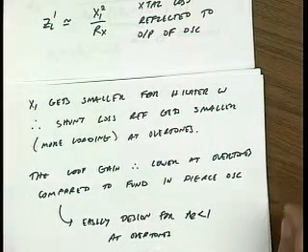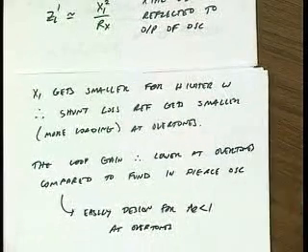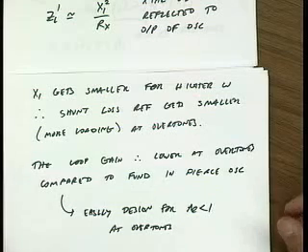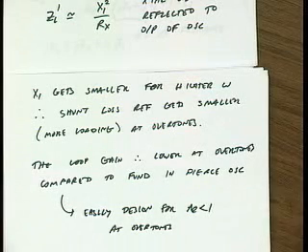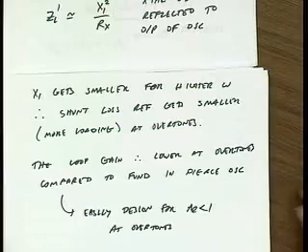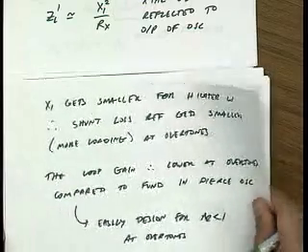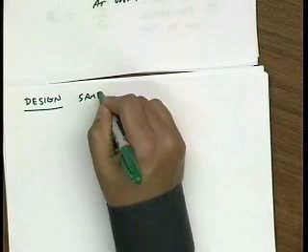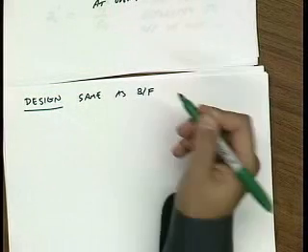And this is important because if the loop gain is bigger than 1 at an overtone frequency, you might actually end up oscillating at an overtone, or you might end up oscillating at 2 frequencies simultaneously. So instead of producing a spectrally pure output, you produce 2 frequencies unintentionally. So let's now summarize the design procedure for this Pierce oscillator. It's in fact very simple. It's really the same. Pretty much nothing has changed.